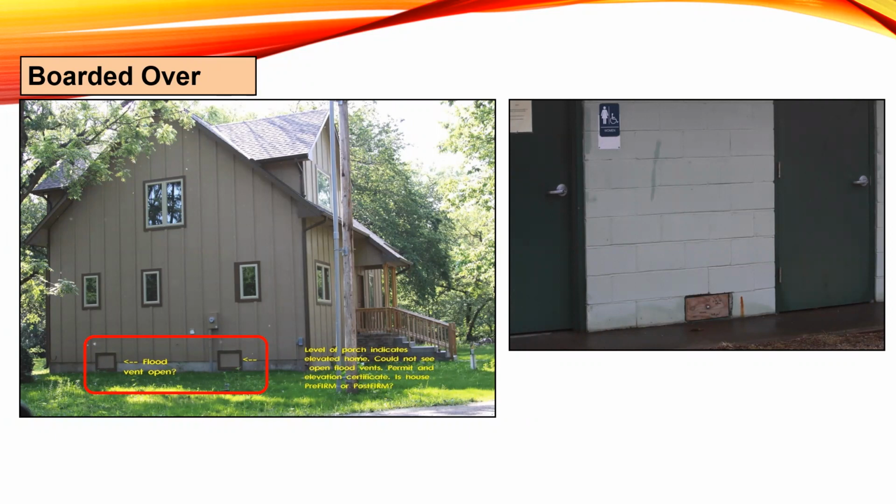We have the flood openings to equalize pressure from flood water pushing in on the foundation walls. And so to equalize the pressure, we have this free flow of water. Otherwise, it could collapse the foundation wall, which is a lot of structural damage. That's going to be big as far as insurance claims or making repairs. It could push someone over the substantial damage threshold.